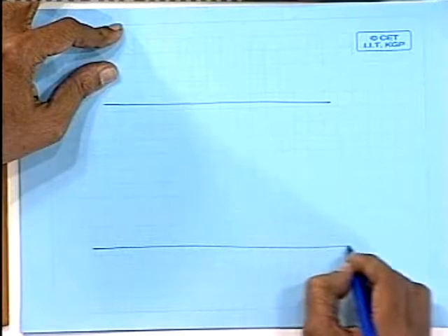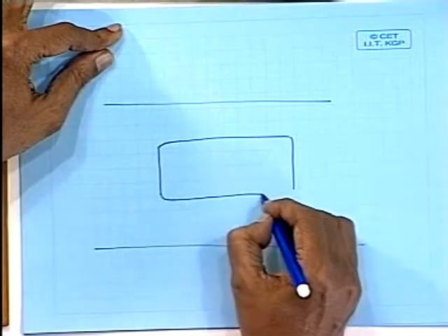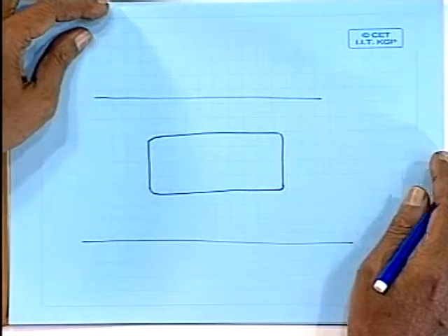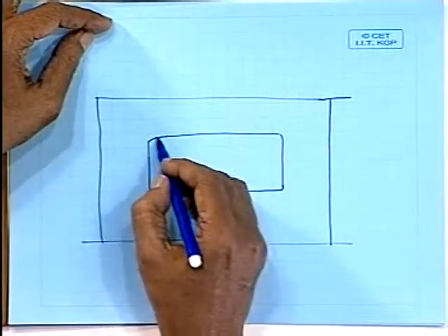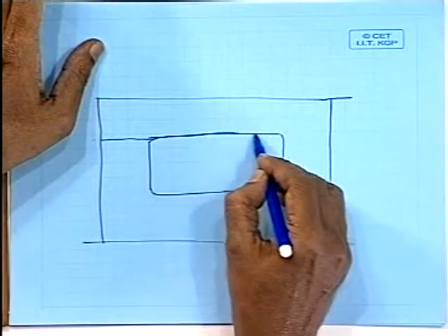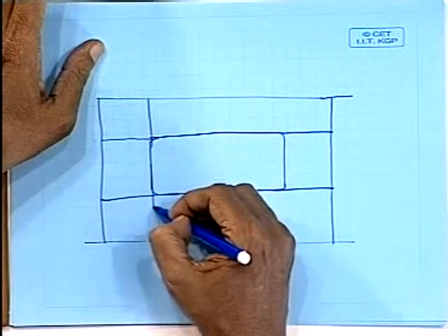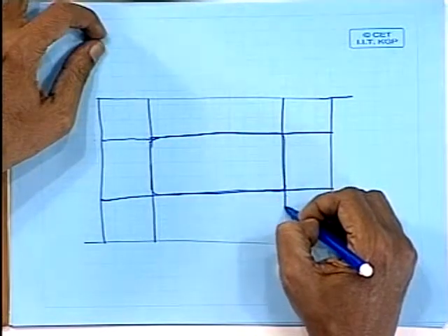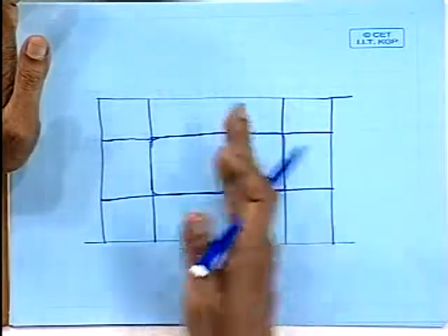The hull girder, sorry, deck girder. This is the hatch opening, right? And there is a bulkhead here, there is a bulkhead here. Now this hatch opening has to be strengthened by hatch side girders, that is, on the side of the hatch the girder has to run, and transversely they have to strengthen by, what are these called? Hatch end beams. These are very deep structures. These are hatch side girders running on the sides, strengthening the opening you have made of the hatch, and hatch end beams.